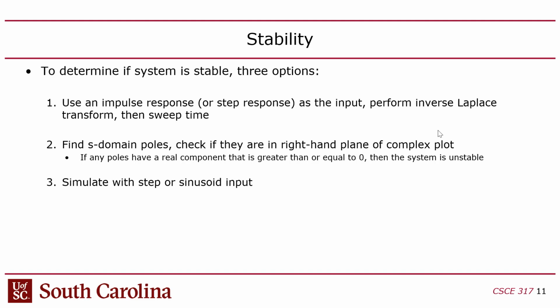One of the ways that's very common is to look at the impulse response. So if you have a system in LTI, you can hit it with an impulse and see how it responds. If the system is unstable, then it will blow up in response to the impulse. Now, first of all, what's an impulse?